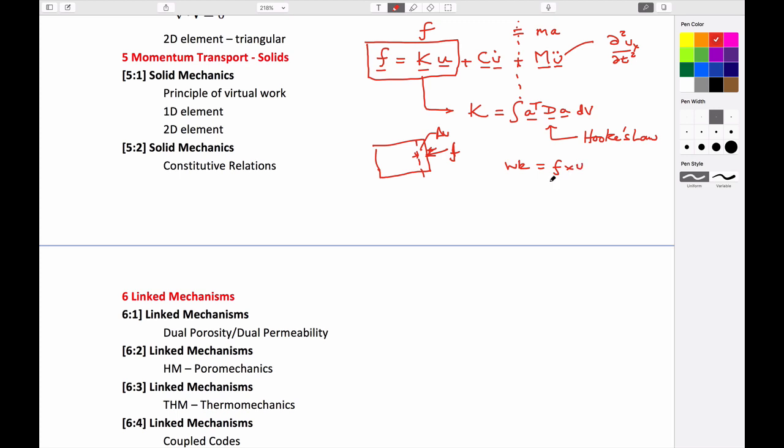So that has to be balanced with what's going on inside this. And so what's going on inside this is it's shortening by some amount. And so this force is applied as a point force, and it goes through a finite deformation delta U. But what it would do is to every single point within this structure, there would be some strain that would be applied, and there would be a stress that was a result also of this same force which is moving in the boundary. And so the external work, you could imagine, is just the force that's applied times the displacement.